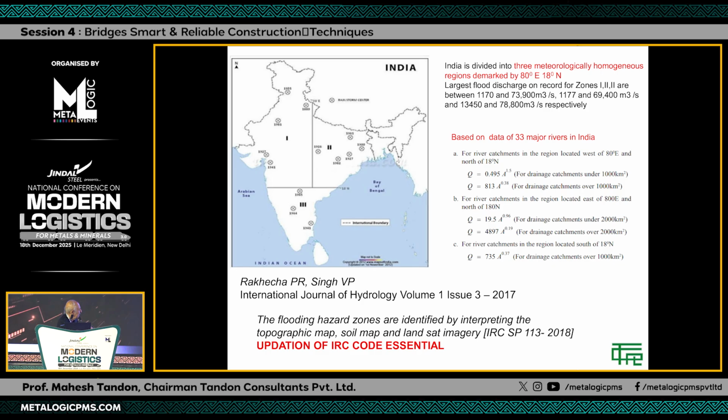that different formulae, which are all empirical, decide what to use for large and small streams or rivers, which formula to use in order to be able to evaluate the discharge. This A, incidentally, is the catchment area, but as we will see, there is not only the catchment area, there are also other things that come into the picture.